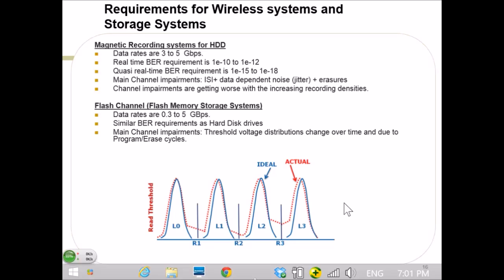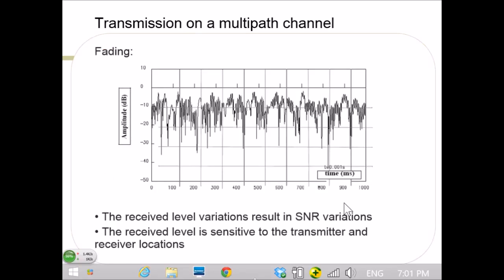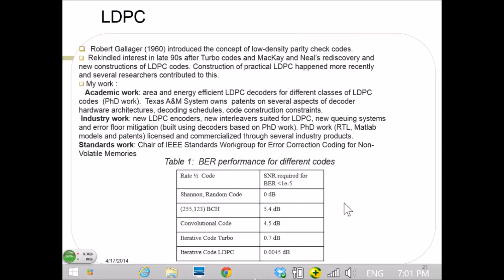So it'll be like Reed-Solomon, convolutional code, more recently turbo code. You should say Viterbi. Well, Viterbi is the decoder. Yeah, it's a decoder for convolutional code. This is an encoder. LDPC is a code, so that's what you encode it with. It's for correcting errors. You add extra parity bits, and you use those parity bits later on to correct errors in the block, or whatever it is, in the data.